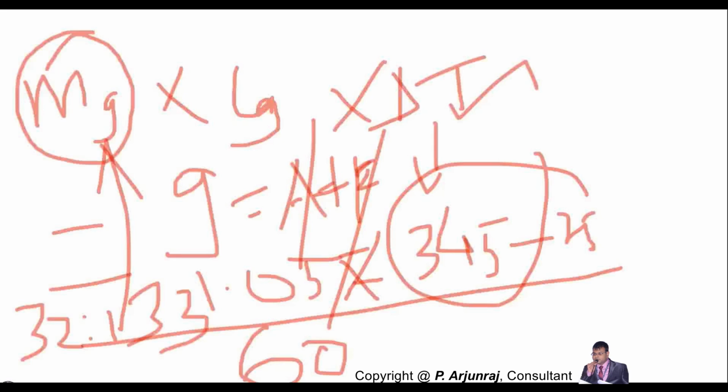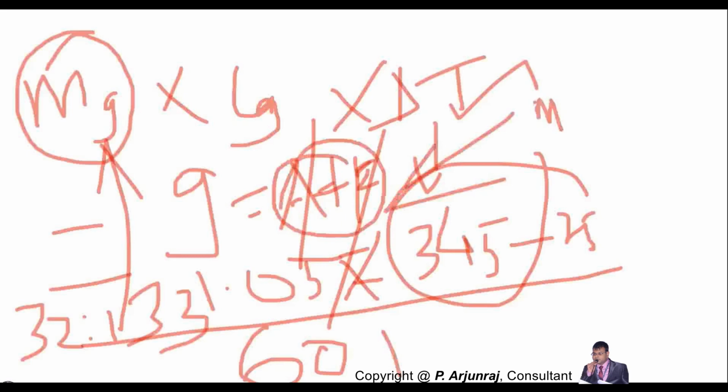So this is nothing but the air fuel mixture, and you also need to see the fuel. The mass flow rate of the fuel is also given in the problem as 2.5. So this 33 into 2.5 will give you the overall heat distributed in the form of exhaust gas.